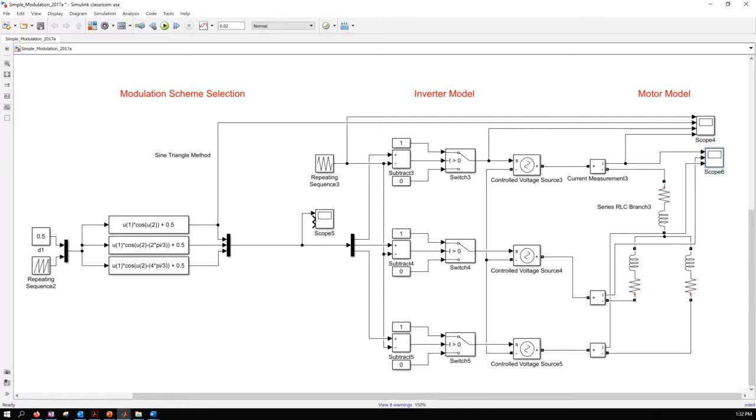In order to have a positive and a negative, your half VDC becomes the 0 point. With respect to that, you have a negative voltage and a positive voltage, which means the maximum phase voltage we can apply with this method, at least for now, is half the bus voltage, right? The peak-to-peak value of your sinusoidal voltage will be VDC, which means the peak value that you can apply is half VDC.